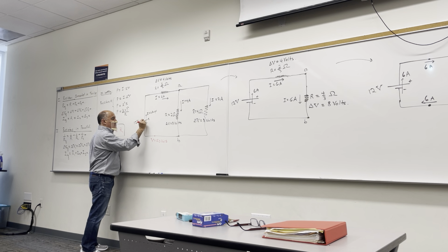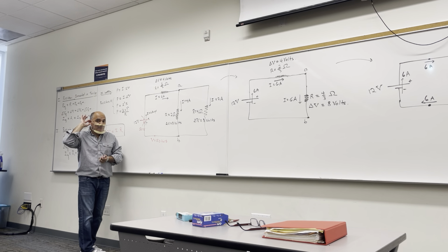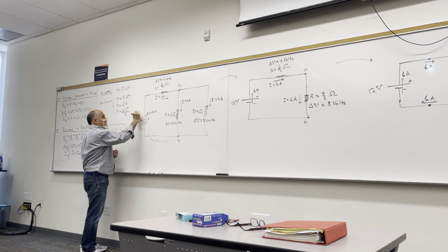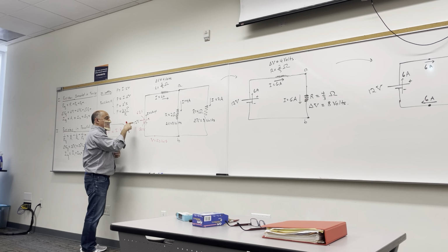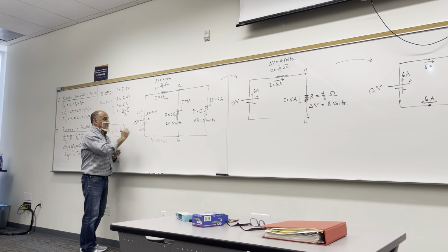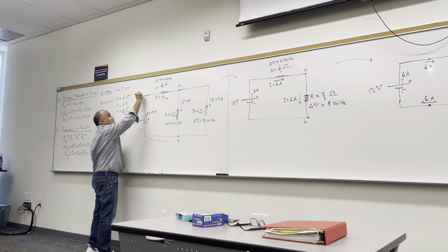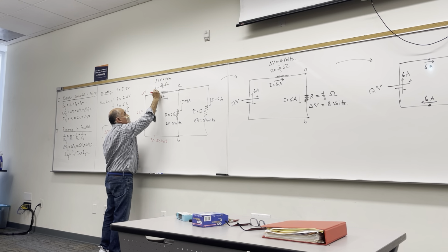What will be the potential here? 72 volts? How much? Or I mean 62 volts. Forgot how to do math. 62 volts. Right? This means that this is the difference between these two potentials. And this one being longer, positive, and this one being shorter, this is of the higher potential. Because the answer could have also been 38. But this is higher potential than this, because this was drawn longer, right? That's why we say that that's plus and that's minus. So this here is 62 volts.